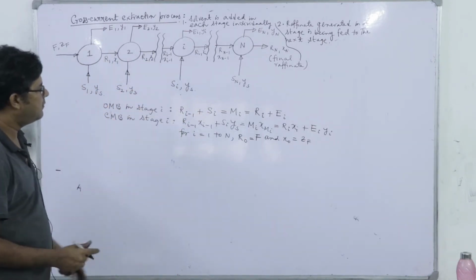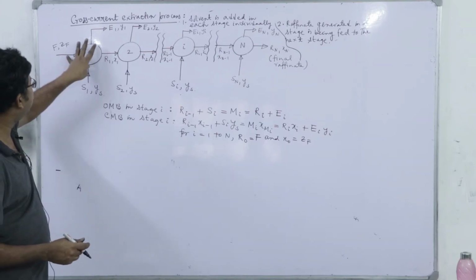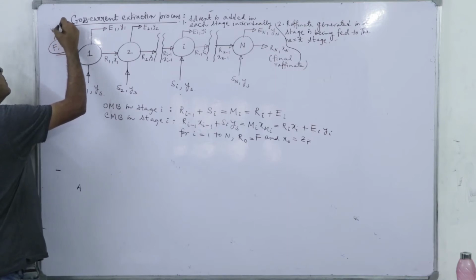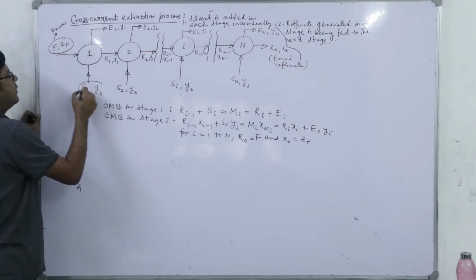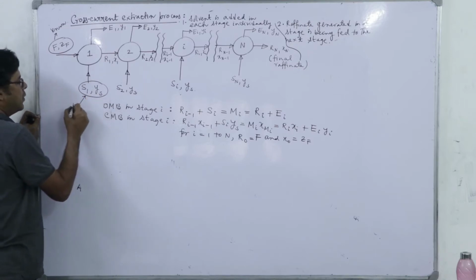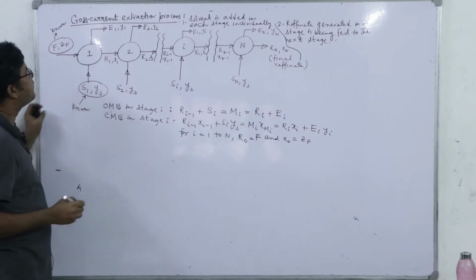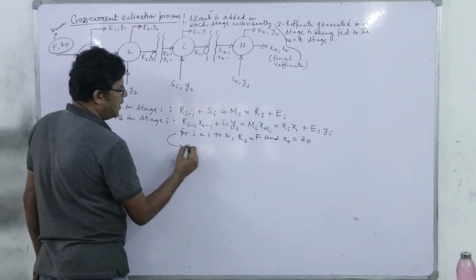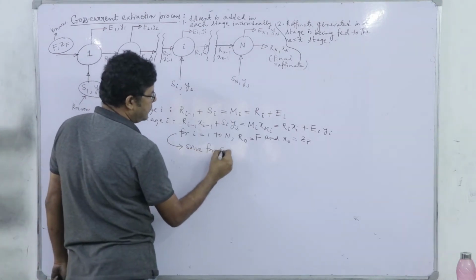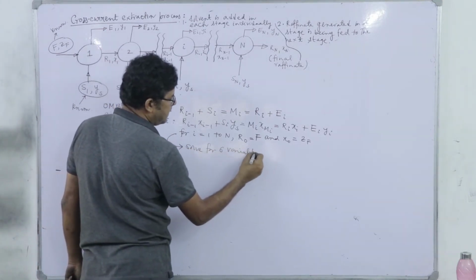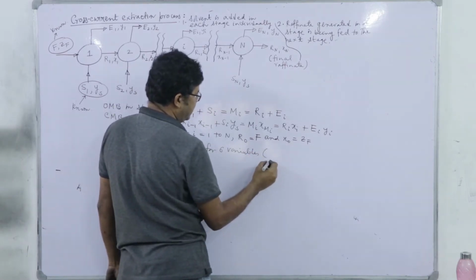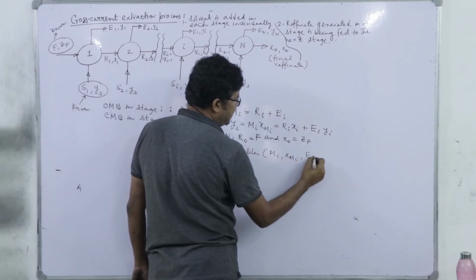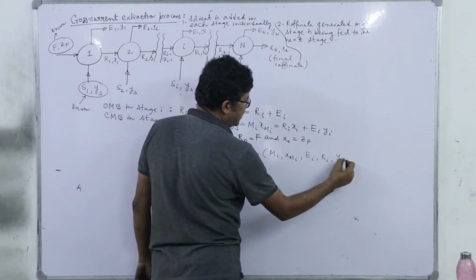Now you see, for individual stages, if I start solving from here, these two values are known, and the solvent flow rate and solvent composition are also known. So we have to solve, according to this equation, for 6 variables, just like the single stage extraction: Mi, XMi, Ei, Ri, Yi, Xi.